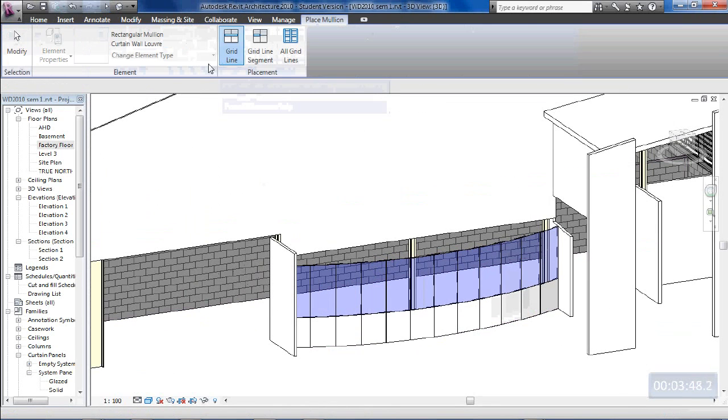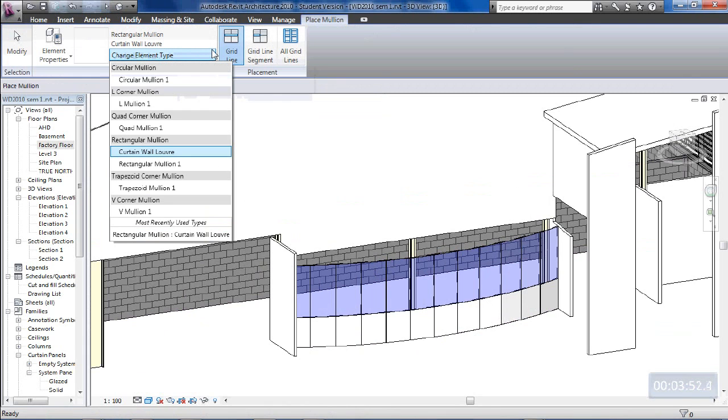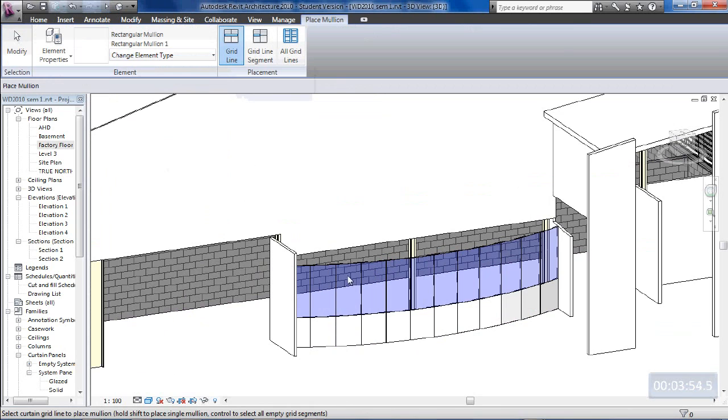The mullion type is not the louver now. We have to select that back and go back to our rectangular mullion. And we'll do, that would have been the head. This would be the transom, and this would be the sill. But to Revit, they're all mullions. They're all the same shape. And so now I will do the vertical mullions, and we've established a glass curtain wall.